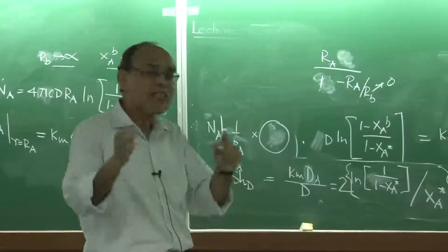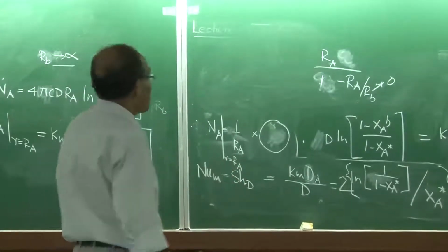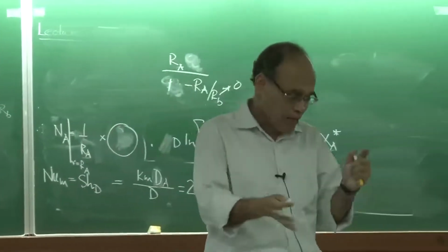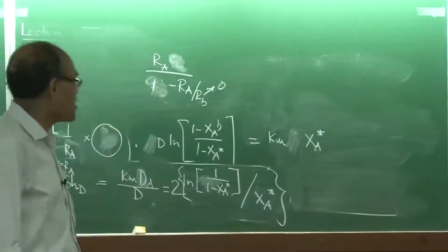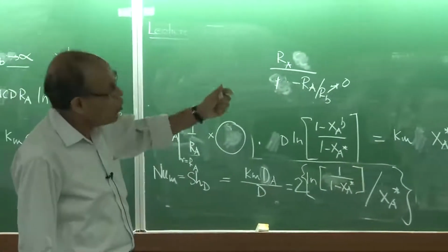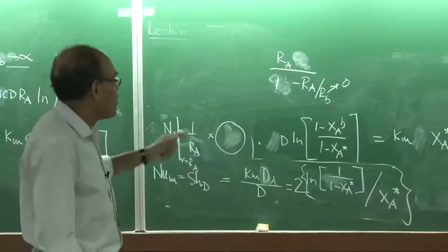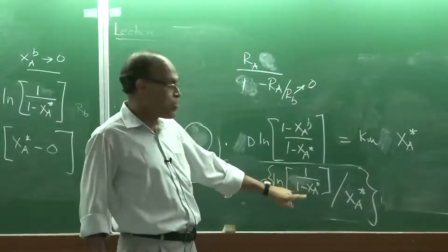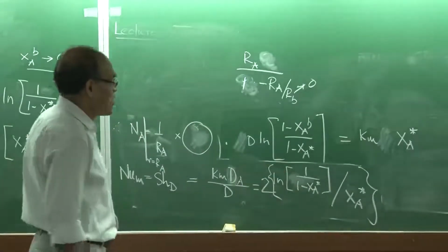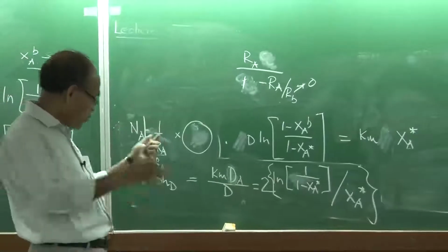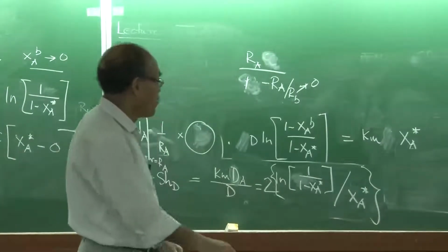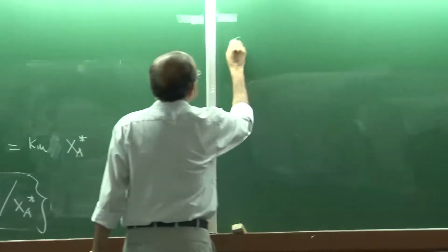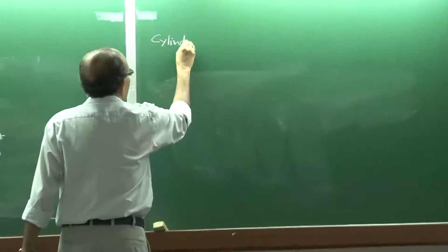But if this equation does not match, for example, in this particular case, when we consider that there is a bulk motion of the gas, then certain factors appear additionally in the equation. Then, although the same steps could be carried out, the final solution may be a little bit different because of the additional parameters which arise from the complexity of drift velocity in the case of a solid or bulk motion in the case of a gaseous medium. We can also do a similar exercise in the cylindrical polar coordinate system, for example.